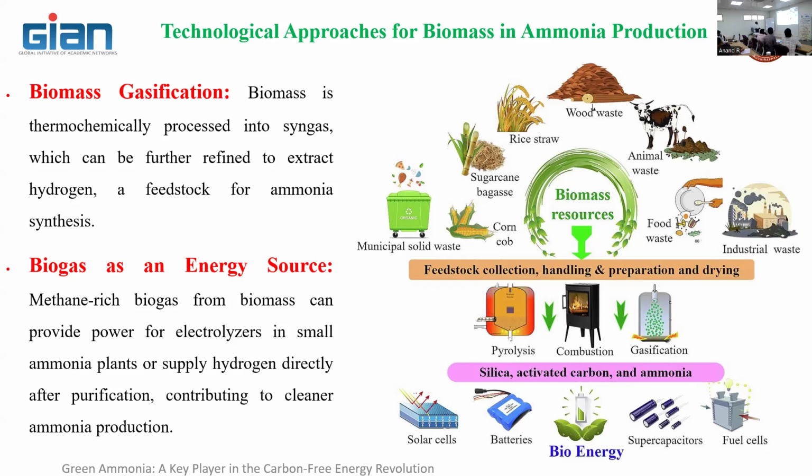That you can take as a raw material for producing bioenergy through the combustion mode, gasification mode or pyrolysis. So in combustion, we will get only the products of combustion in the form of gas, the end product. Whereas in gasification, you are going to get solid, liquid, and gas. Here the gas is predominant. Whereas in pyrolysis, you are also getting three products, solid, liquid, and gas. But here the liquid is predominant.